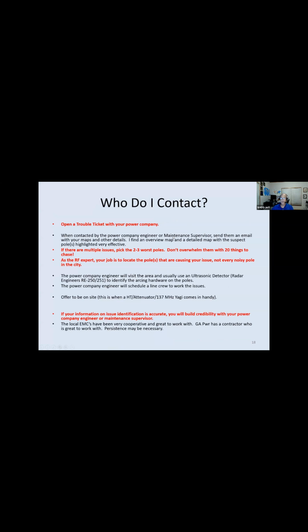I try and keep the number of issues I report at one time down to a reasonable level. You can go out and find all kinds of noise sources, but you really want them to fix the ones that are causing you problems. So you don't want to give them one 2 miles away. That's probably not your issue. You want to give them the one that's half a block away or a block away. So when I do the survey, I try and find the 3 biggest offenders clustered in an area. I'll give them those 3 things to work on.